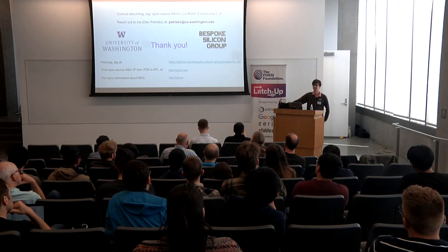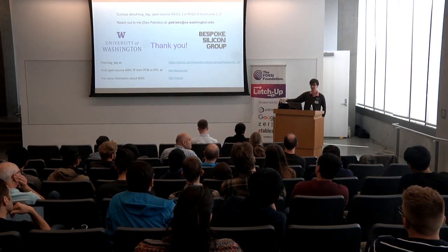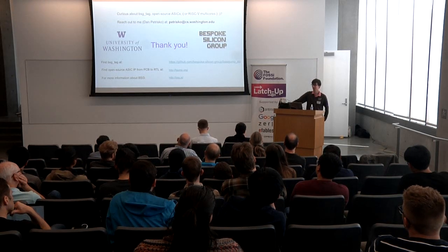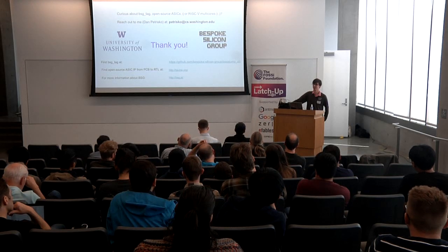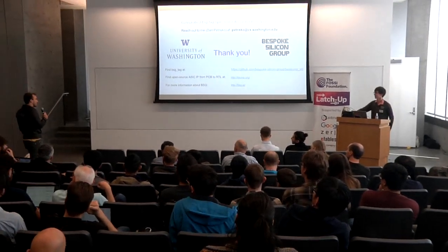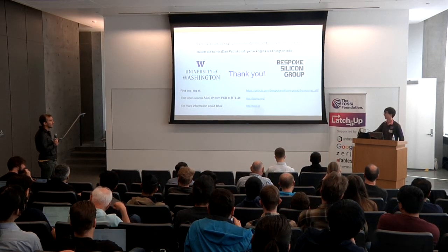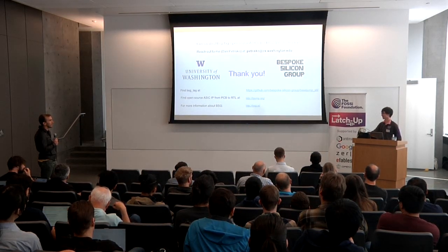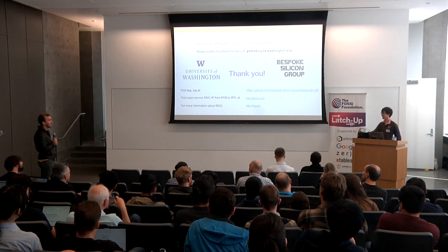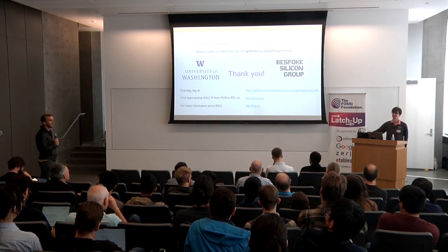Generally some statically configured muxes, so that subsets of the chip can read out those individual values. It's hard to do it in a scalable way to get all the signals out without doing a scan chain. How complex would it be to make it bidirectional, JTAG style, just shift something out? You can do it. It requires a lot of toolchain integration usually to do it automatically, and it's a huge pain to do it manually.